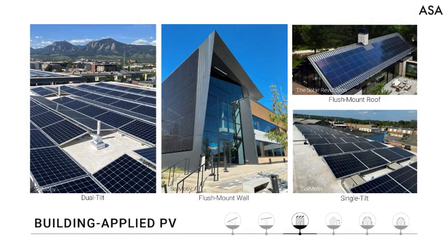Building applied PV typically consists of single tilt or dual tilt systems, as seen on the right and left side of this image. Tilt-up arrays for flat roofs are typically wind tunnel tested at a set tilt and various inter-row spacing options. These systems are more cost-effective than specifying customized spacing that requires a more conservative approach to analyzing wind loads. They can be either mechanically attached or ballasted.